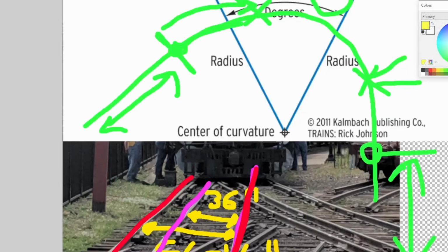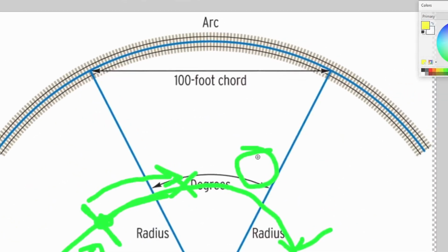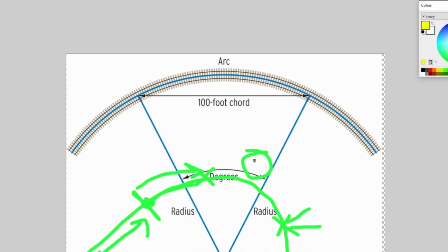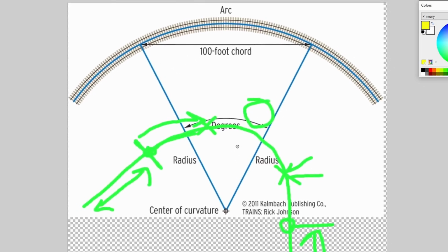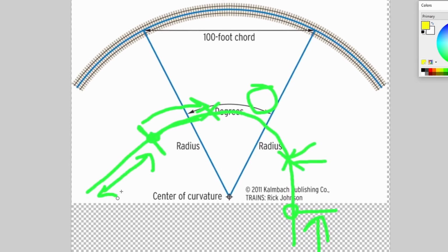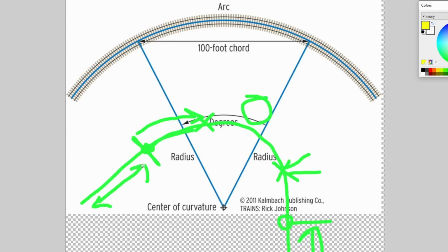And the last important unit of measure for a railroad is curvature, where we have degrees of curvature because we have to measure things in the real world, but you can calculate the radius out from that. And typically, if we have higher speed trackage, rather than just using a chunk of a circle, we will have a tangent straight piece of track, a spiraling in piece of track that goes from straight to the degree of curvature. Then we'll have a constant degree of curvature, constant circle, spiral back out, and then straight piece of track again.